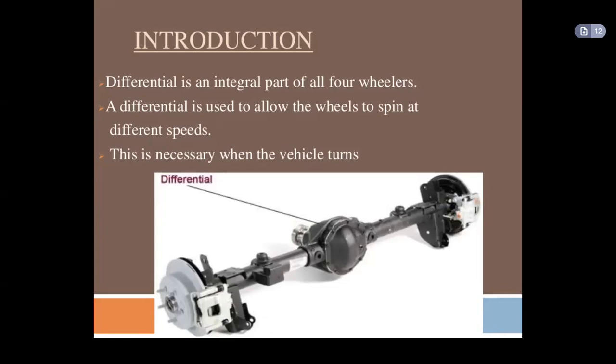If the vehicle is going in a straight line direction, in that condition the spider is not rotating on its own axis, because the adjustment is not required in that case. So the spider is only rotating along with the ring gear and is not self-rotating about its axis.